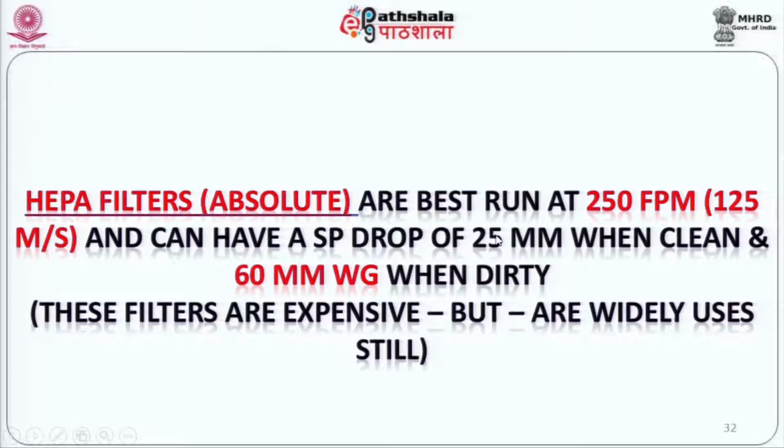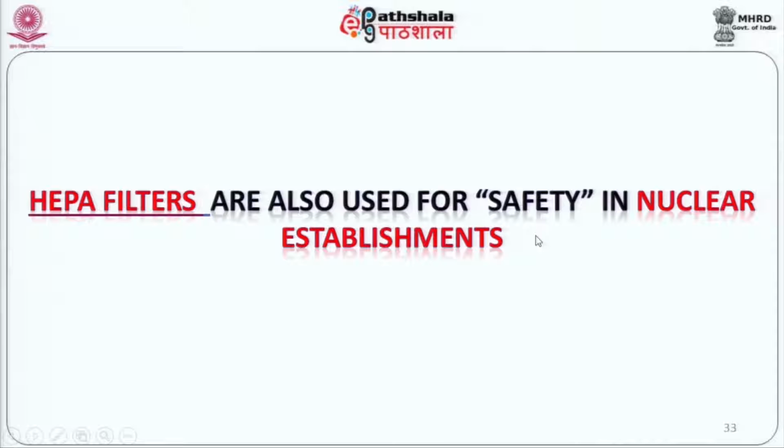Now the impact of these high pressure losses on filters is that the older systems would operate at very low static pressure, which means the fans were very small, whereas if the air conditioner has got to be fitted with a HEPA filter, one needs a more powerful fan which will work at maybe very high pressures of nothing less than 60, maybe even highly 100 mm. Another use for HEPA filters is also obviously when you use them for safety purposes in nuclear establishments, because in nuclear establishments also it is basically dust which is normally sought to be controlled.